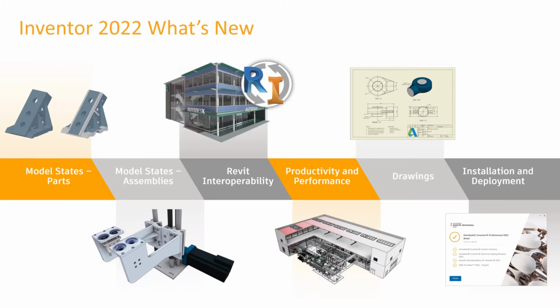A couple of other things with regard to drawing enhancements, and again, quite a number of enhancements here with regard to camera views and manufacturing information. Lighting styles from your 3D model can now be included in 2D drawing views. So if you've set up a lighting style that particularly highlights certain faces or edges of your model and you want to see that on a 2D drawing sheet, we can now use those lighting styles from the 3D model and carry them forward into our 2D drawing views in the IDW or DWG environment. So a number of different options there with regard to some performance enhancements as well.